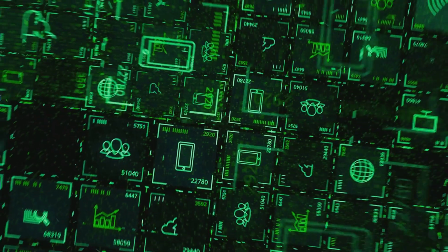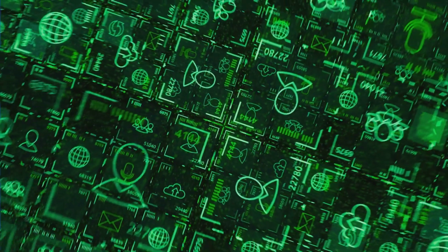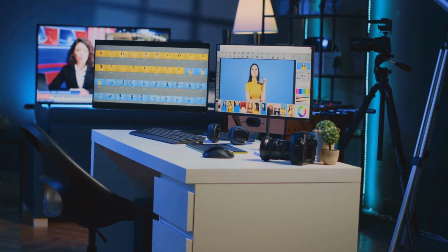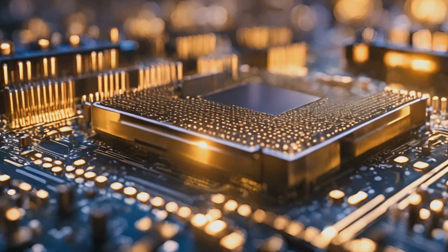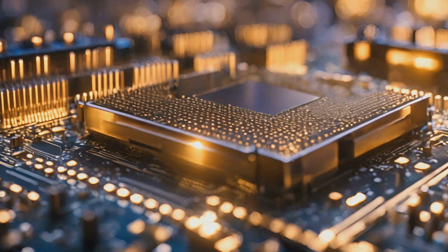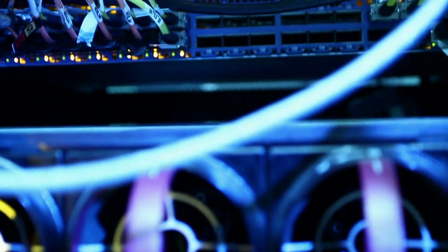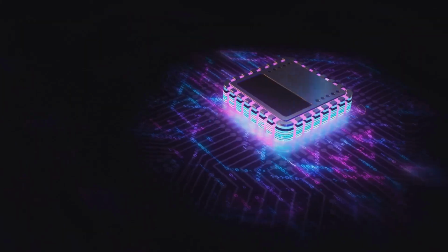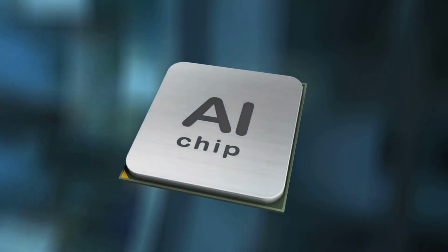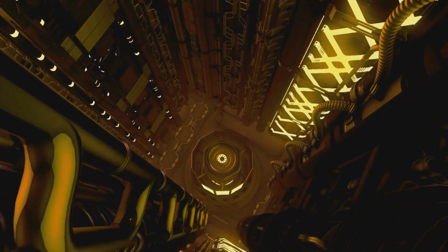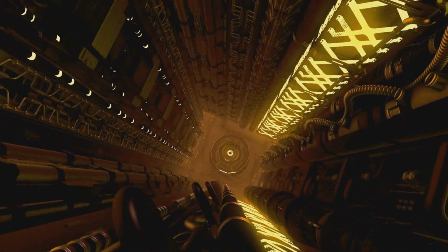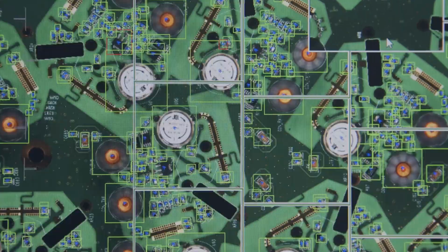The speed and width of a bus are critical to performance. Bus width is how much data can move at once, like the number of lanes. A 64-bit bus moves 64 bits simultaneously, making it faster than a 32-bit bus. Bus speed, measured in megahertz, is transfers per second. If the bus is too slow, it becomes a bottleneck. Even the fastest CPU must wait if it can't get data to and from memory or devices quickly, just like a sports car in a traffic jam.